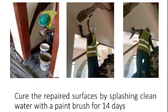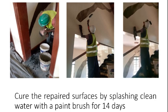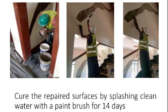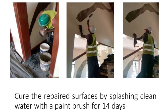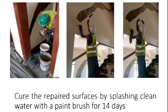So you must allow it to cure, give it time, splash with water, cure the repaired surfaces by splashing clean water with a paint brush for a minimum of 14 days. Don't be in a hurry. You allow it to fully cure. Curing means that the cement and the sand and the blocks are added together. So that's just a demonstration to show how this is done. All right. So you just brush carefully and also make sure you inspect the other walls.